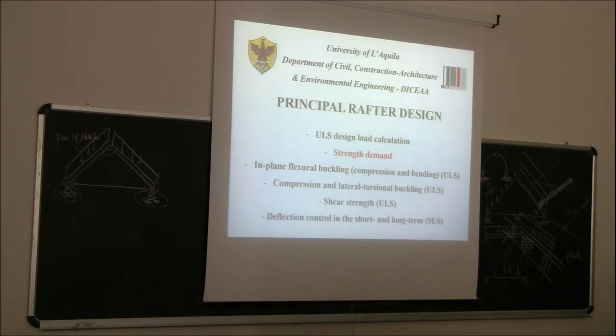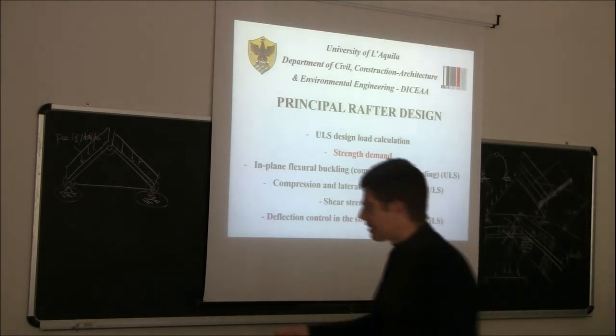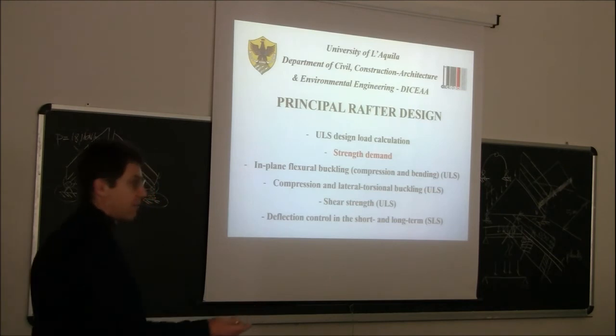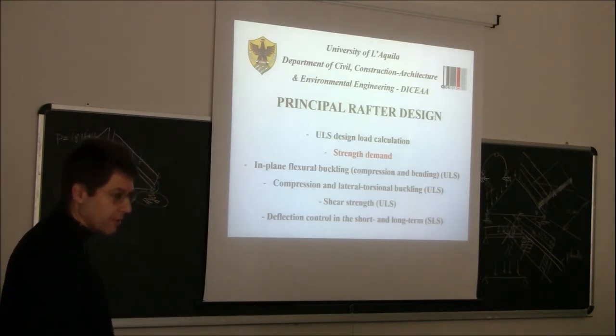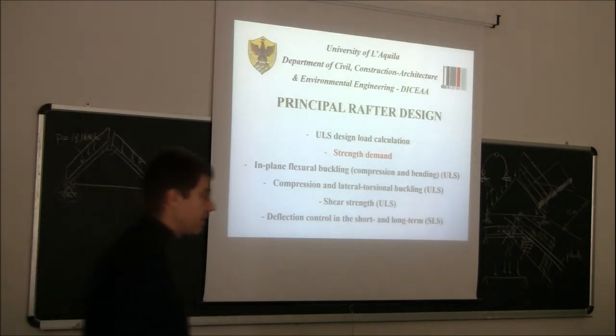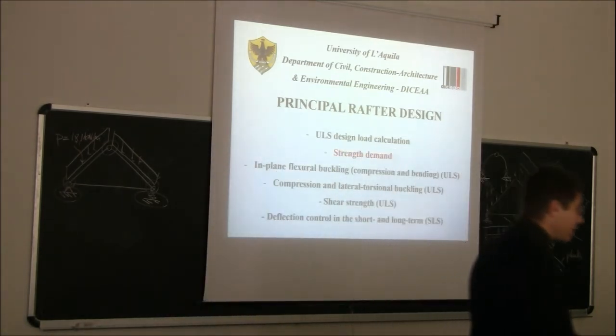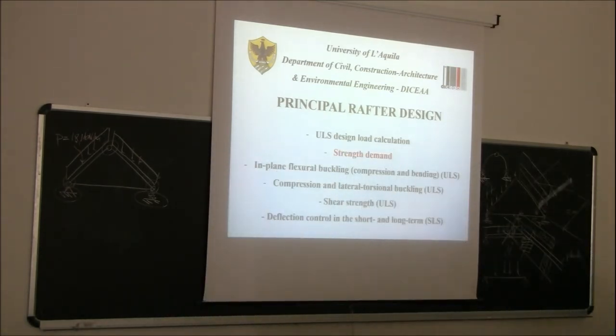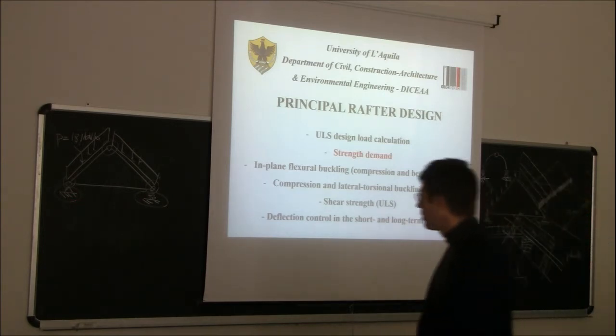Can you repeat? Yes, now we are counting. Since we are not sure whether this system is statically determinate or statically indeterminate or even unstable, we are counting the degrees of restraint, the number of degrees of freedom that are cancelled out by the restraints. So we have 3 internal pins, and then we have 2 external restraints. So we need to count how many degrees.